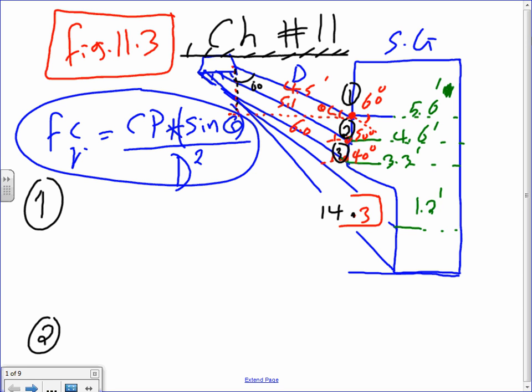So my goal and your goal is to do vertical foot candle calculation on these 3 points. If you look at this, this is point 1, point 2, point 3. These are 3 points, and I'm supposed to do a vertical calculation on these 3 points. I have a fixture in the ceiling directed to shine on this face of this switch gear, and I need to do calculation at point 1, point 2, point 3.